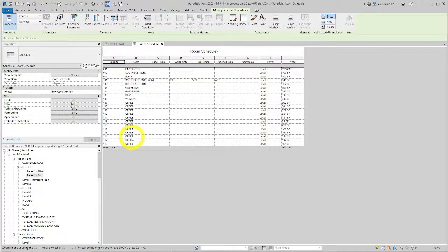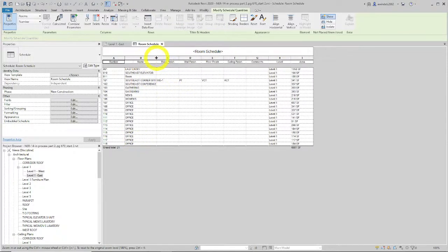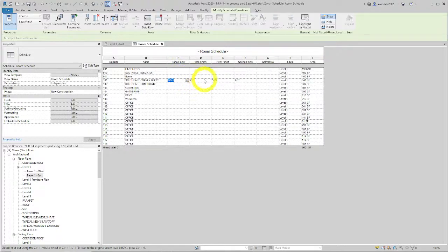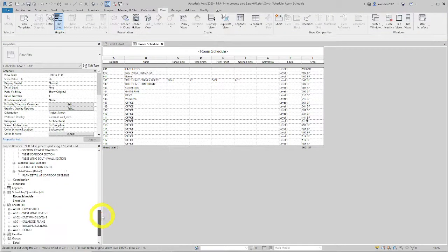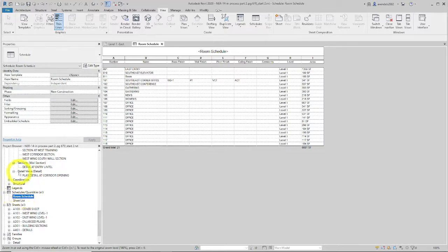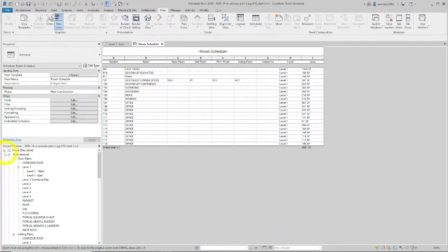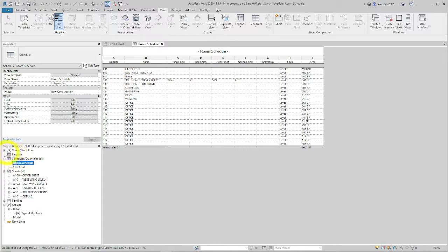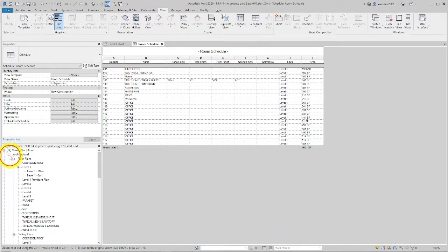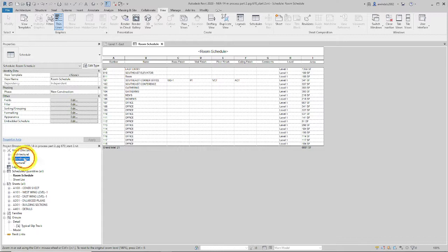It's a mistake. All we're going to do here, instead of editing this in the properties like we did before when we selected that room, remember we got these 4, we're going to edit it in the schedule now. And these schedules, this is kind of important, easy to miss, they populate down here. So this just populated way down here. If I cascade everything in my project browser down, they're below my architectural coordination. We'll have some coordination ones later, but this is where they populate.